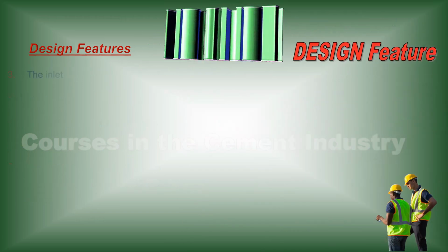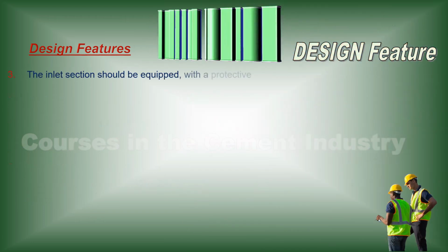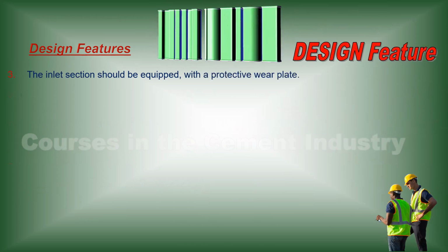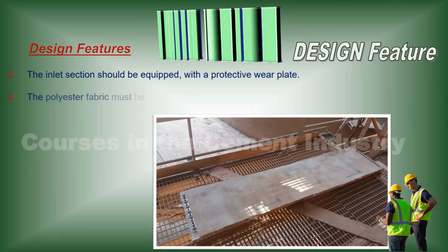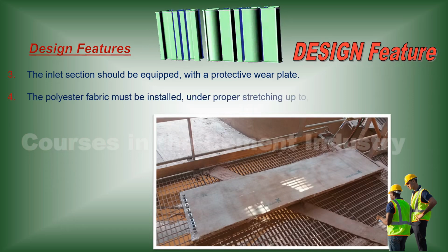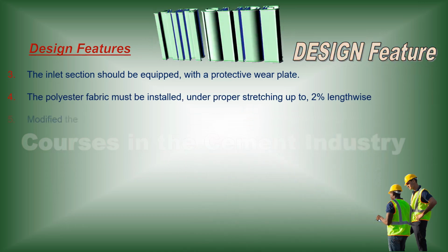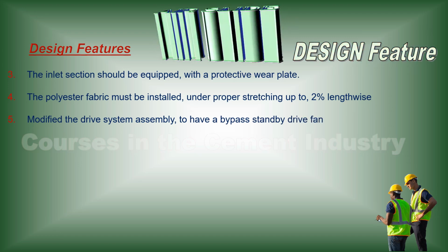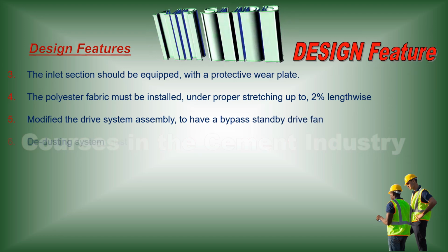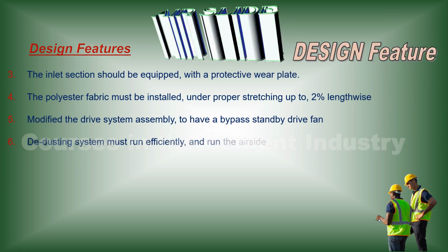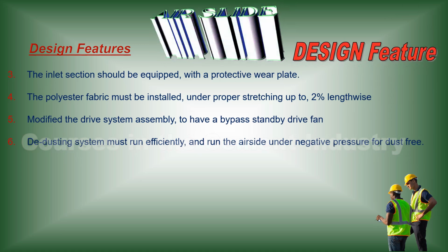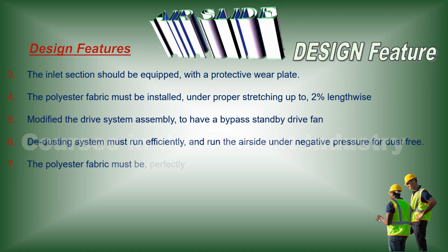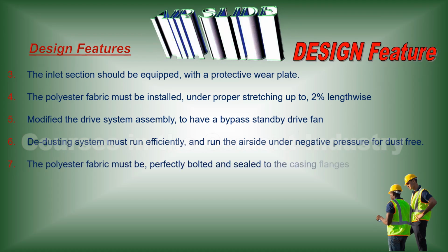3. The inlet section should be equipped with a protective wear plate. 4. The polyester fabric must be installed under proper stretching up to 2% lengthwise. 5. Modify the drive system assembly to have a bypass standby drive fan. 6. The dedusting system must run efficiently and run the air side under negative pressure for dust-free operation. 7. The polyester fabric must be perfectly bolted and sealed to the casing flanges.